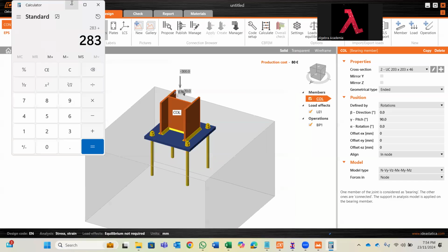Now coming back to the edge distance. How much is the edge distance? The minimum edge distance as per code is 1.25 times the diameter of the bolt. The minimum diameter of the bolt for a structural section should not be less than 12 millimeter, right? So 1.25 times 12 millimeter is 15 millimeters from the center of the bolt. But 6 has already gone, because you are measuring a 12 millimeter diameter bolt. In that case, you will get only 9 millimeters. That is not feasible. So what the code is trying to say is that you should maintain the edge distance. It is mandatory to go with minimum 1.25 times the diameter of the bolt.